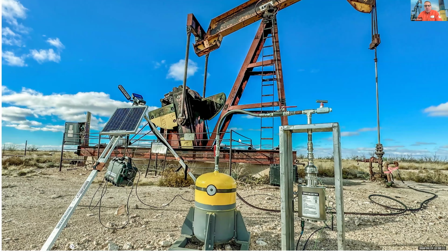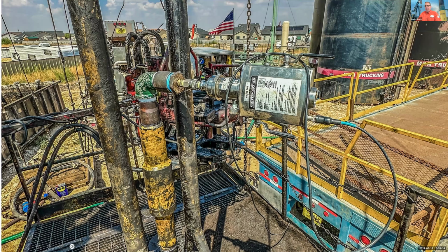Here's another shot where we're actually working on a well in southeast New Mexico in the neighborhood. You see the proximity of the homes in the background and actually a mobile home park that's less than 100 feet away. This particular well came from, again, courtesy of a defunct operator and was just ripping gas to the atmosphere. So we're in there working continuously with the plugging crews to not only do the pre-plug methane emission certification, but also through the process to see what the stage integrity is of those plugs as they're coming up out of the hole.